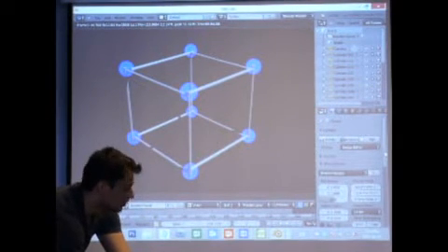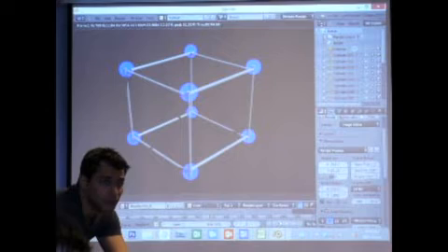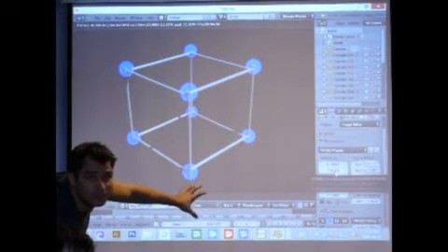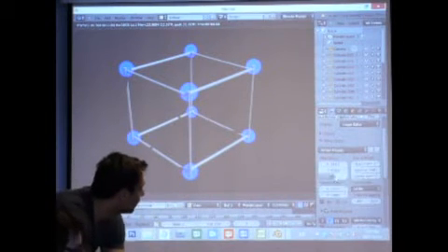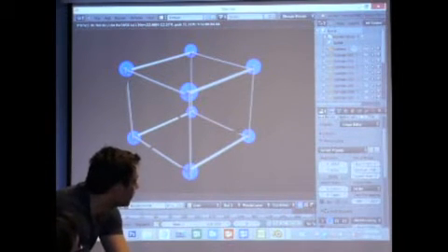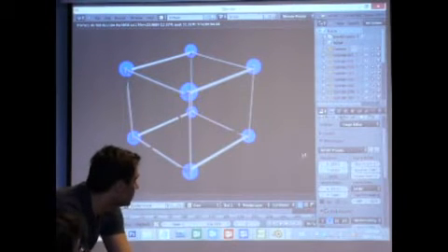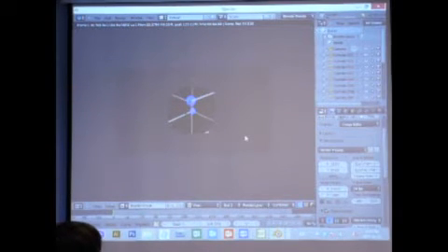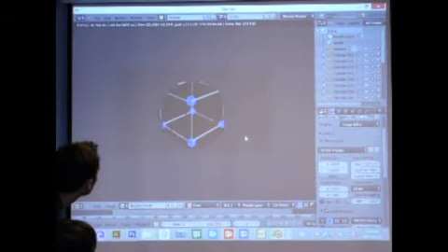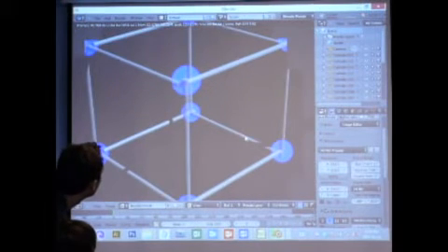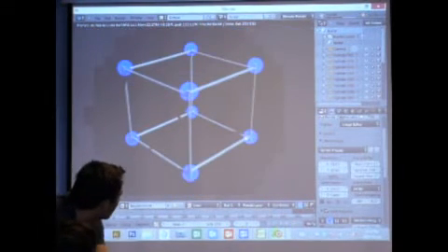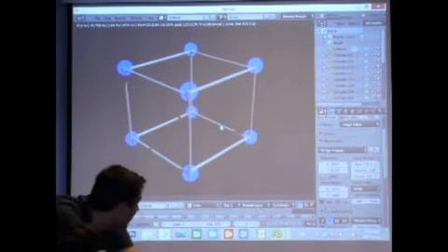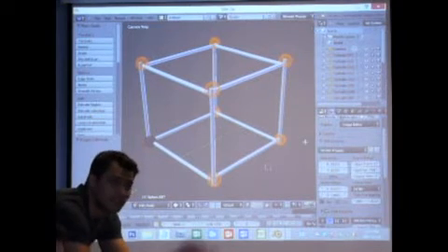So right here is resolution. That controls the actual size of your image. Right now, we're creating 50% of the size of the 1080p picture, 1080 pixels high. If I change to 100%, so exactly this resolution, it will take a little bit of time, not too long. And you can see the actual resolution is pretty good. But if it takes way too long to render, you can just press escape. You just mash escape, it'll stop.